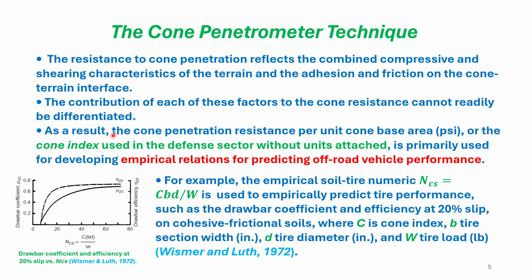As a result, the cone penetration resistance per unit cone base area, the cone index in psi, or the cone index used in the defense sector without units attached, is primarily used for developing empirical relations for predicting off-road vehicle performance.